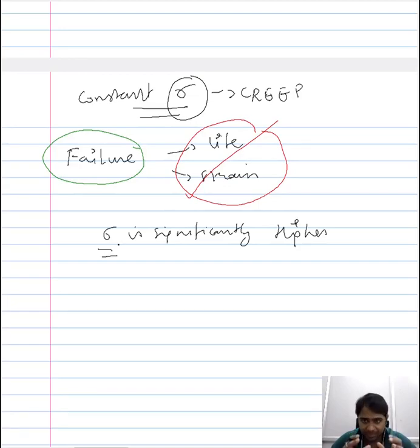So this test approach is carried out in a setup similar to that of creep, wherein the temperature is involved and you measure the strain with respect to time. All this framework would remain the same. The only change is you have shifted your focus from life and strain to failure. So the difference is you would be employing a stress condition, a mechanical condition, that is significantly higher than the one you would use for normal creep.